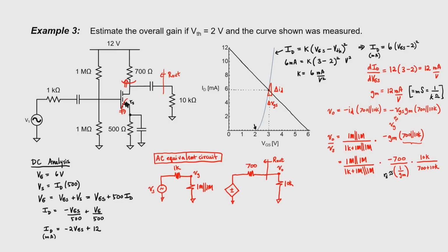And when I see a common source amplifier, I'm just going to remember that the gain here is given by this resistance, which is 700, divided by all of these resistances down here, which in this case is 1 over Gm. So we need to put 1/12 down there in the denominator. The gain is then given by an input voltage divider. We've already written it here. A gain segment, as we've noted here, and an output voltage divider, as we've noted down over here. So the net gain is minus 7.8 when you plug in all the numbers.